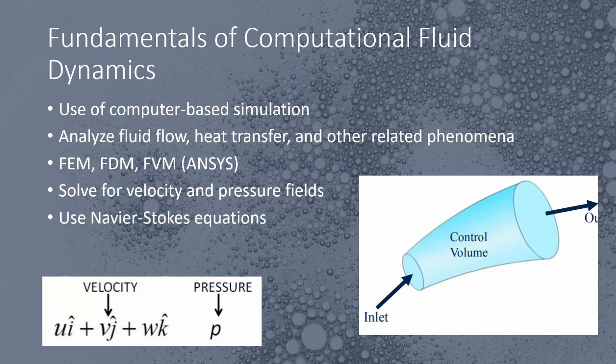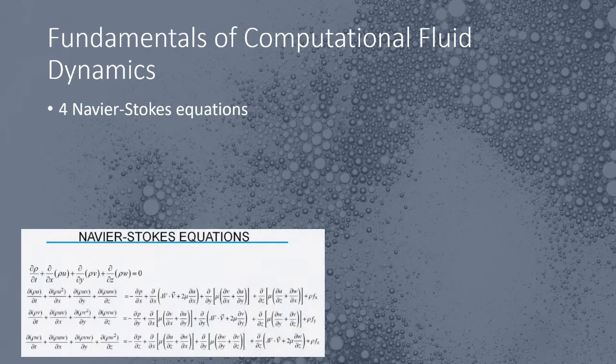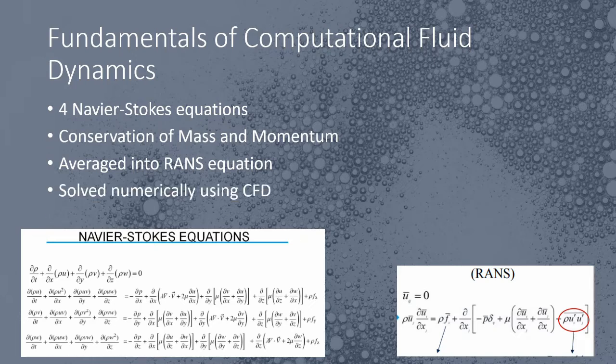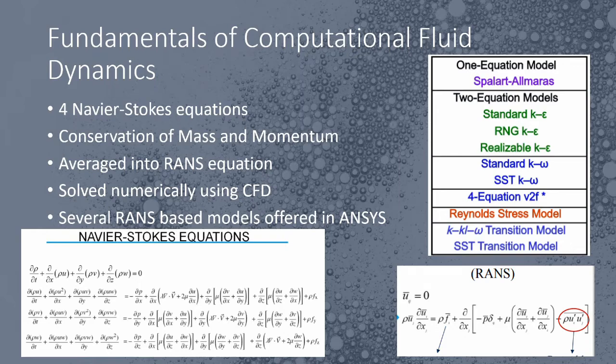And it uses Navier-Stokes equations, conservation of mass and momentum, averaged Reynolds equations, solved numerically using CFD, several Reynolds-based models offered in ANSYS.